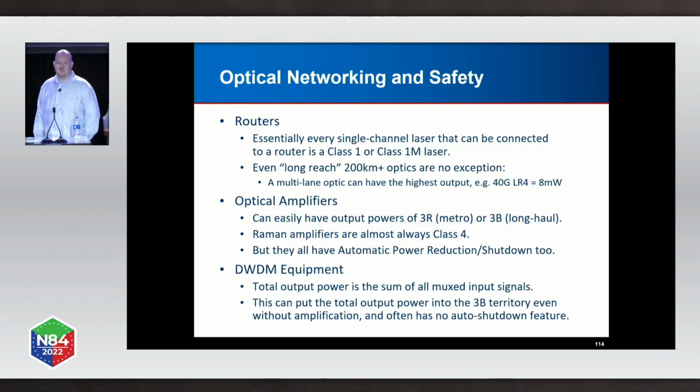The only time you move into anything that's interesting is when you move into optical amplifiers. So now you're starting to put out power levels that really matter. You're in these like plus 21s. There's modern PAM4 systems that are like plus 27, which is class 4. Raman is always class 4. Ramans are very bright, so be careful if there's a Raman amp. But these all by law have to have these automatic power shutoffs. But if you're working and you're plugging in your 10 gig or your 100 gig LR, it doesn't matter.